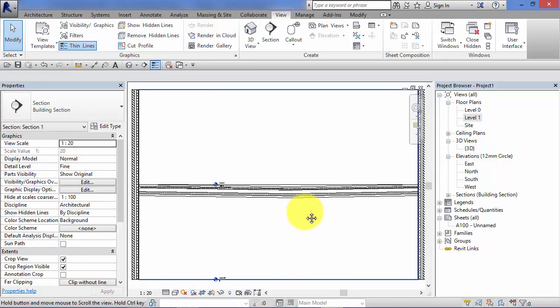As we discussed previously, in most cases that's probably not what you actually want to happen. You'd want the vast majority of these layers to be horizontal and parallel, and then one of the layers, typically screed or maybe an insulation layer, to actually taper to make the top sloped surface. I'm going to show you how to do that now.